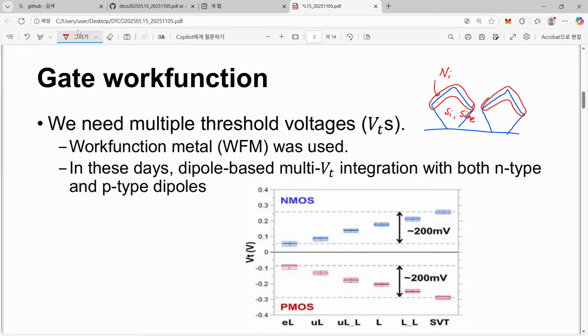By the way, at the end of our previous lecture, after the lecture was over, one student came to me and asked about silicon phosphide, the use of this for doping for N MOSFET. Usually, in many cases, when we use ion implantation for N-type doping, high density N-type doping, we use arsenic.